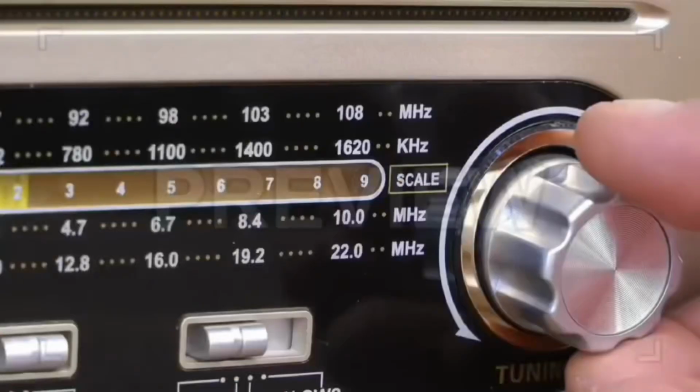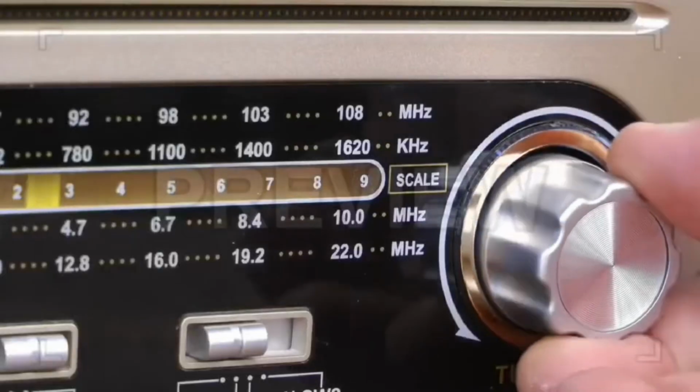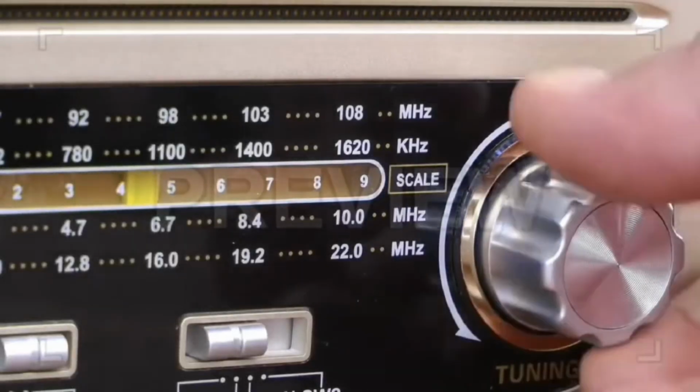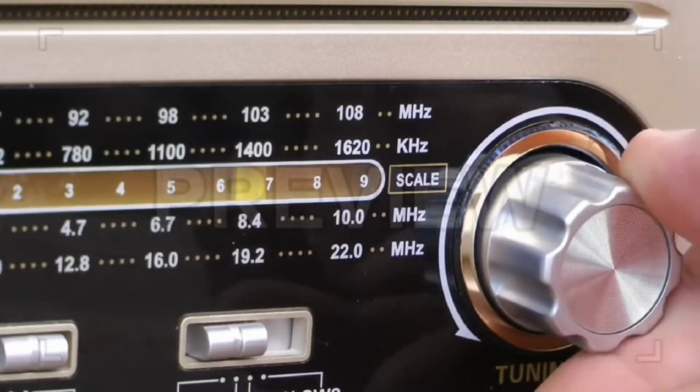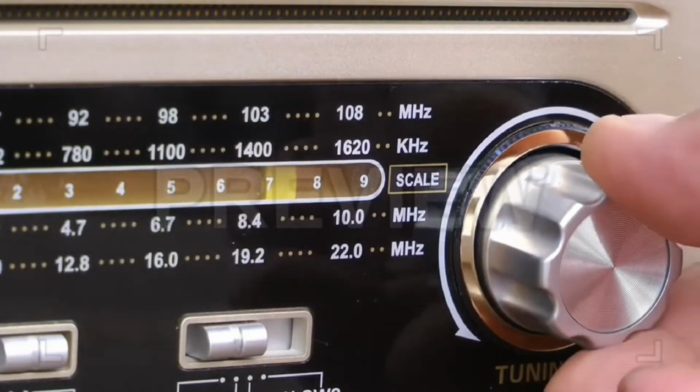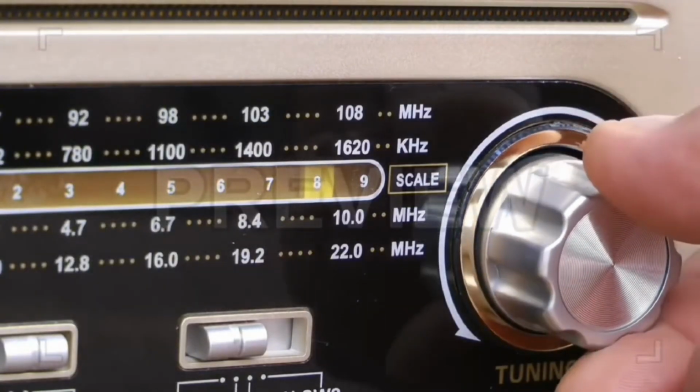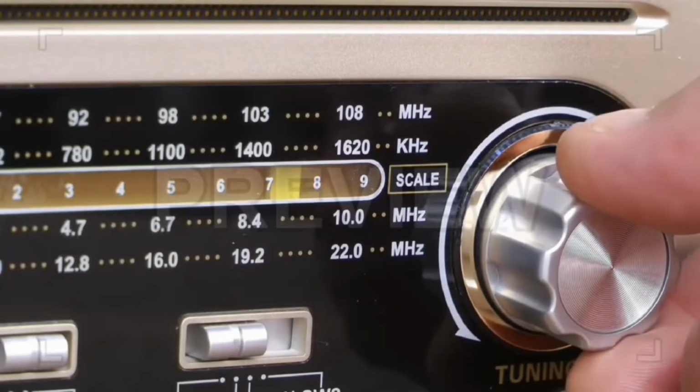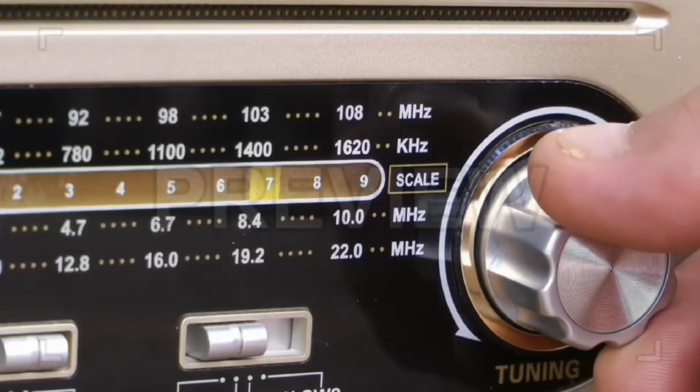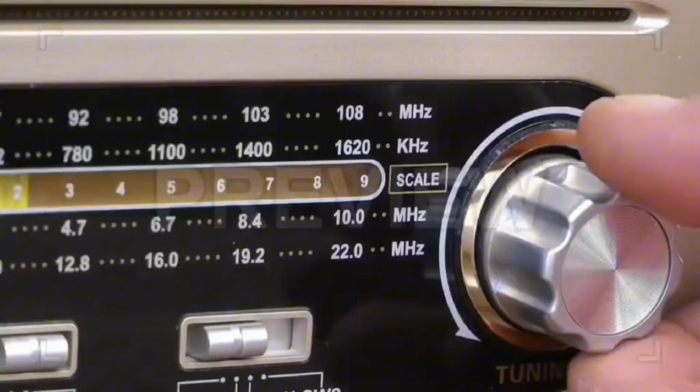Now, watch what happens when the dial of a radio is adjusted. The capacitance inside the circuit is changing, and by that, XC also changes. At one specific frequency, XL equals XC. They cancel completely. The impedance drops to just R. The current is at maximum.